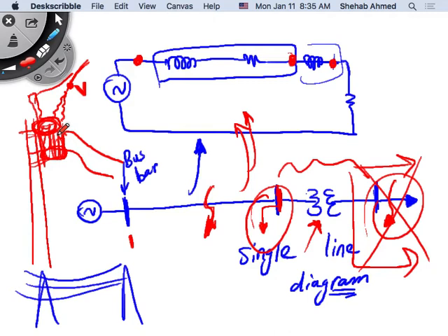So you bring two electrodes with a 30 kilovolt voltage difference, 1 centimeter apart, and they will cause an arc. Move them to 1.2, assuming this air has no humidity. There are certain conditions for the air. I don't know them off the top of my head. Assuming certain conditions for the air, then the arc will not occur.